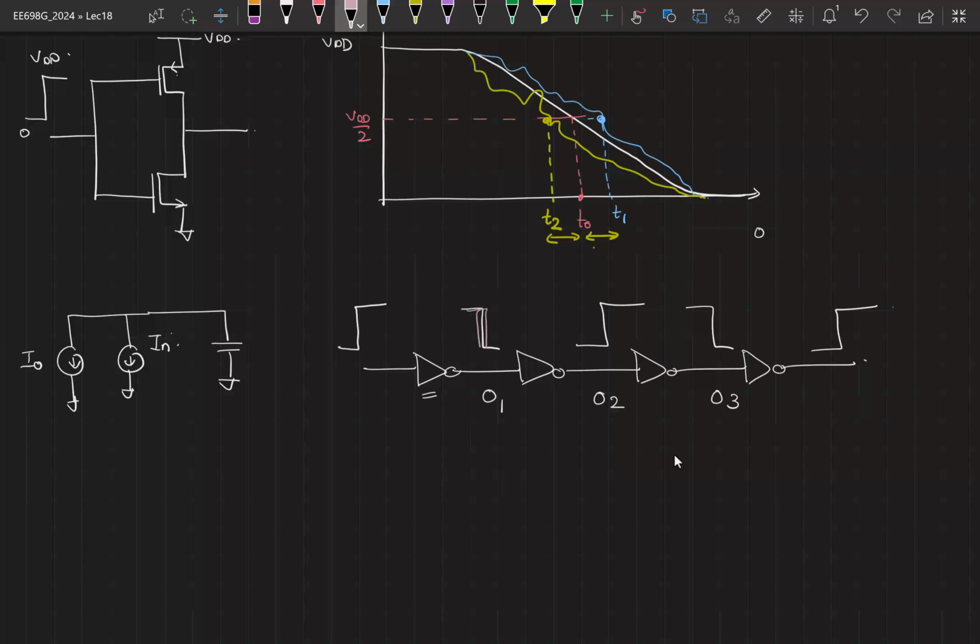Let's say the associated RMS here is some sigma J1. Or in other words, the power in the jitter sequence at the instant O1 is sigma J1 square. Can you comment on whether the jitter corresponding to O2 is going to be greater, smaller or equal to sigma J1 square? Why greater? Because there's already jitter calculated.